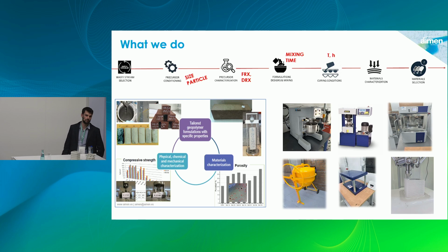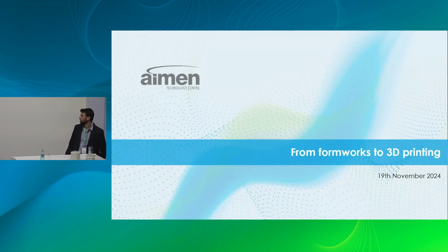Once we have selected the waste, we start with geopolymerization. We use different alkaline activators, different admixtures in order to achieve a material with specific properties for a certain application. And for that, we have equipment related to manufacturing. We have also 3D printers and equipment for testing and analysis.